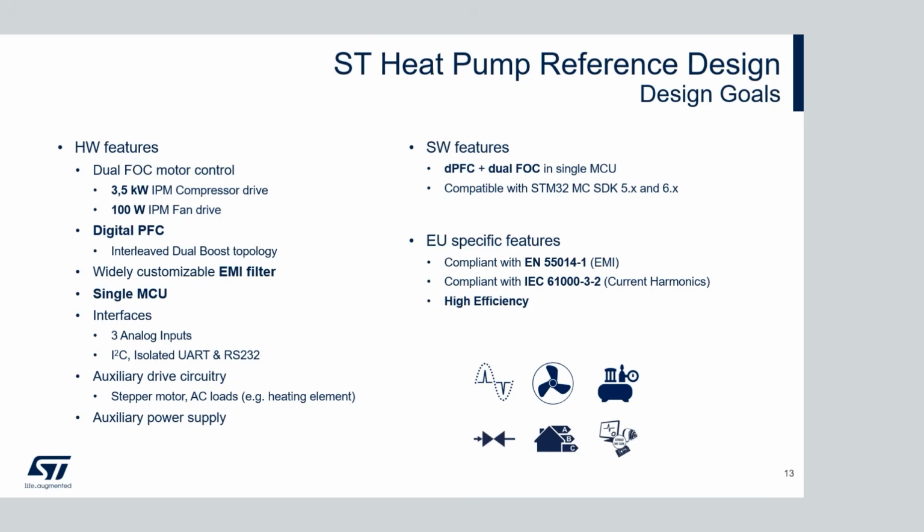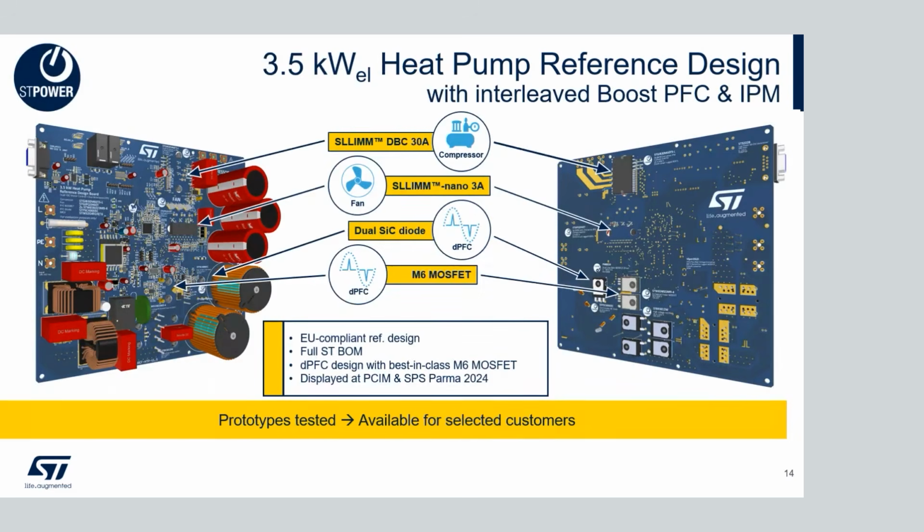And we've also got some need for interfaces for communication, for the sensors, some auxiliary drive circuitry, and also an auxiliary power supply. And we also decided to show that we can control all of these features with a single MCU, and that means driving both the PFC and the dual field-oriented control of the motors with one MCU of the STM32 family. So the result of this work is the reference design like you can see here. It is already available to selected customers and has already been shown at a few trade shows.